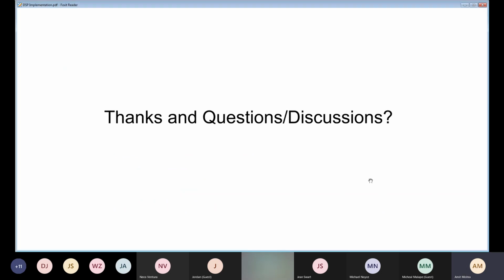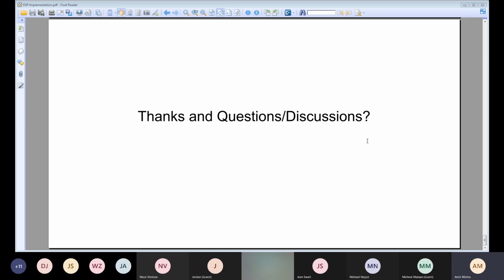Okay, that's kind of the end of the talk. So basically, we discussed two things. Number one, that we can represent DSP algorithms like a network, which is called DFG. And once that representation is there, we can borrow different rules. And one of the rules that we can borrow from network theory or graph theory is retiming, which will basically help us to reduce the critical path, and thereby it will also help us to make the speed of the whole process much faster.